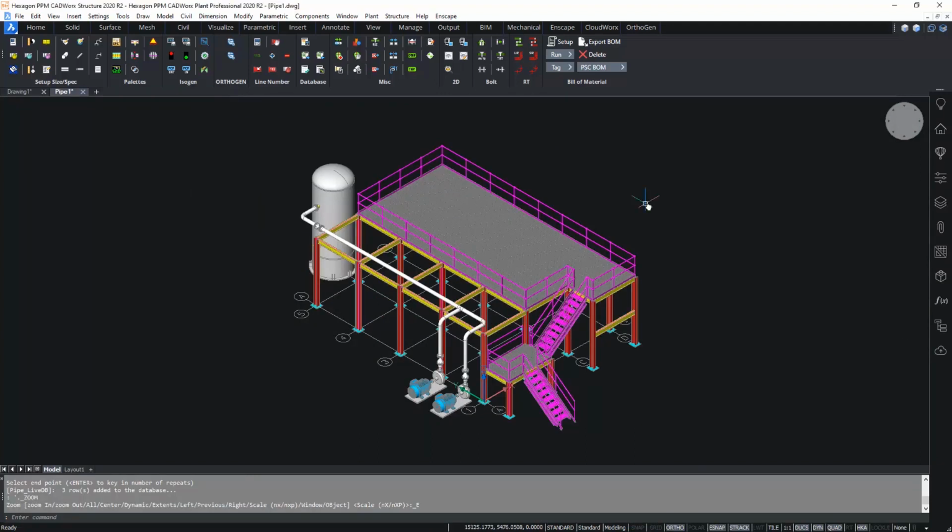finish off by creating an isometric drawing. Okay, now the isometrics are generated using the Isogen engine. However, in order to be able to use Isogen, you need to set up and configure a style, which is done using the program called iConfigure. There are a number of template styles, so I'll show you how to create a basic, simple style based upon the template. Of course, it's entirely configurable, however that would be another video.